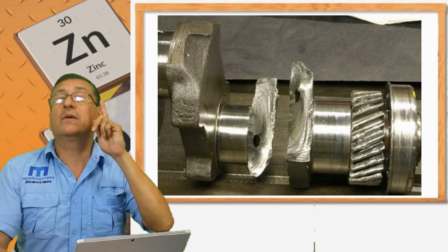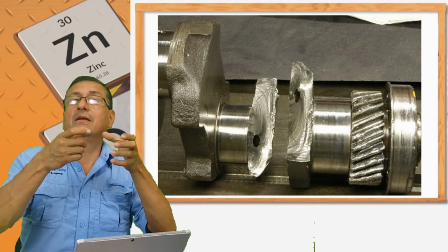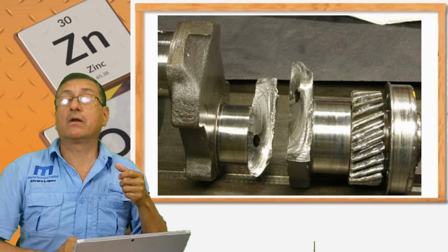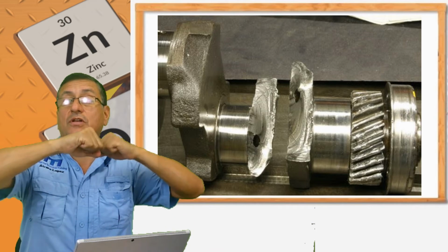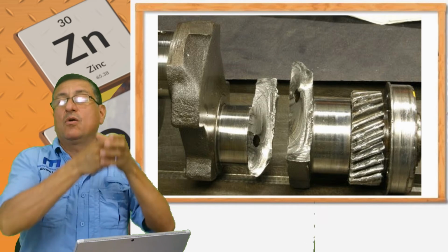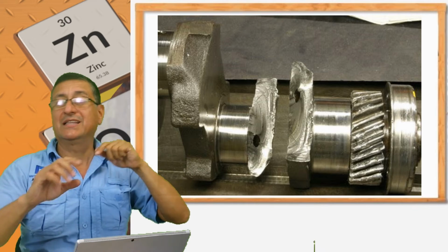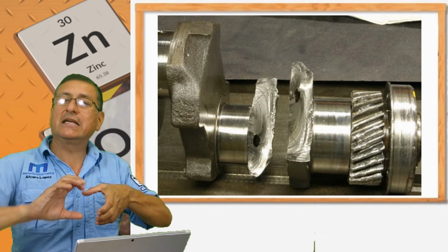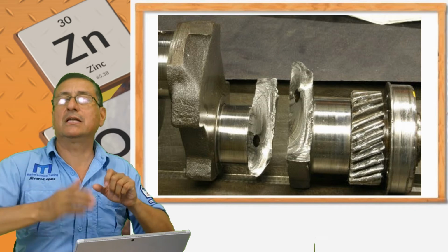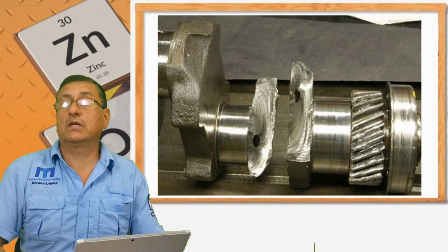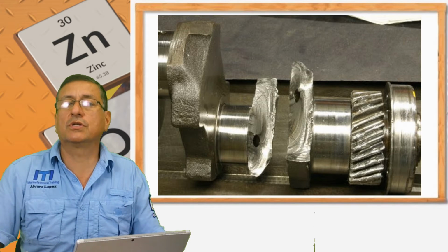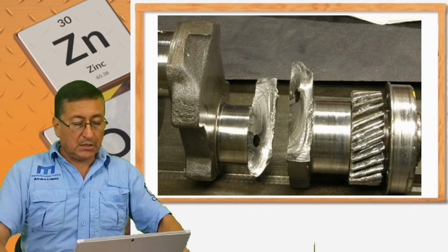When one of the pistons receives salt water, you remember what happened with the piston? The piston expands and blocks the engine. When that piston is blocked, the rest of the crankshaft tries to continue the rotation and is cracked, fractured in that cylinder. Yes, it's very common in diesel engines because of the excessive torque produced by diesel engines.